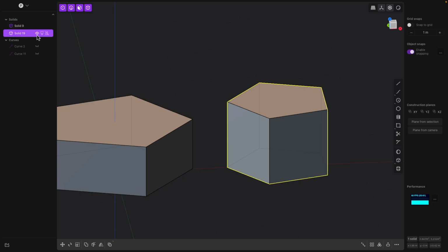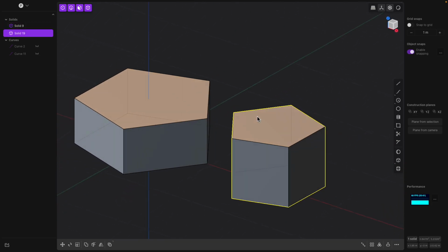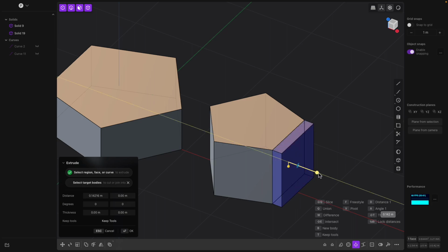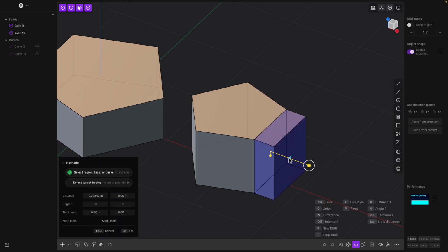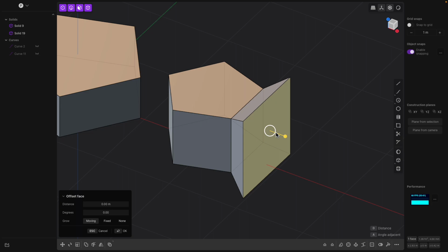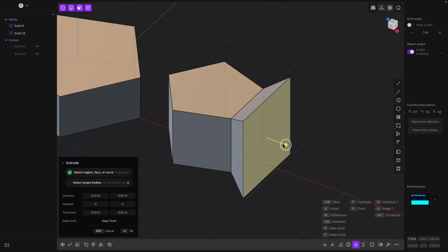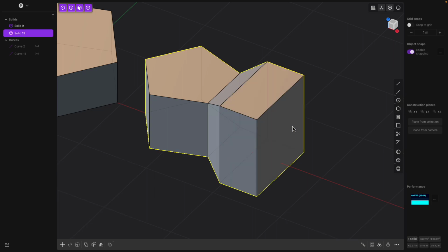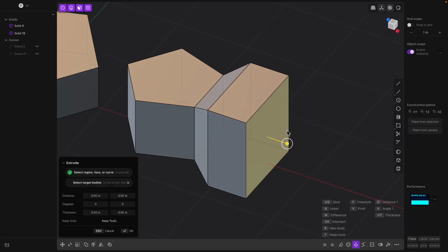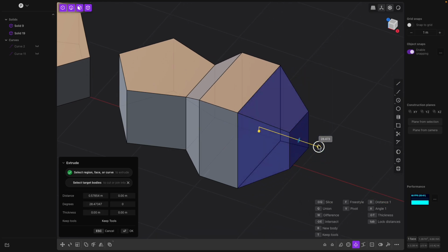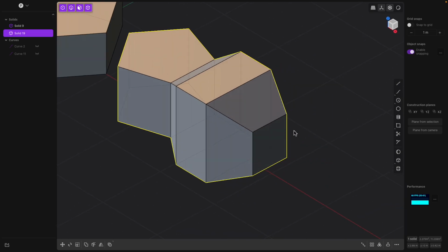Now it's becoming solid. Now that it's becoming solid, maybe it's easier to do the extrusion, things like that. I don't know, so far. Anyway, E is extrude. Right click is to finish the operations. E, extrude. And we can scale, of course. Right click.